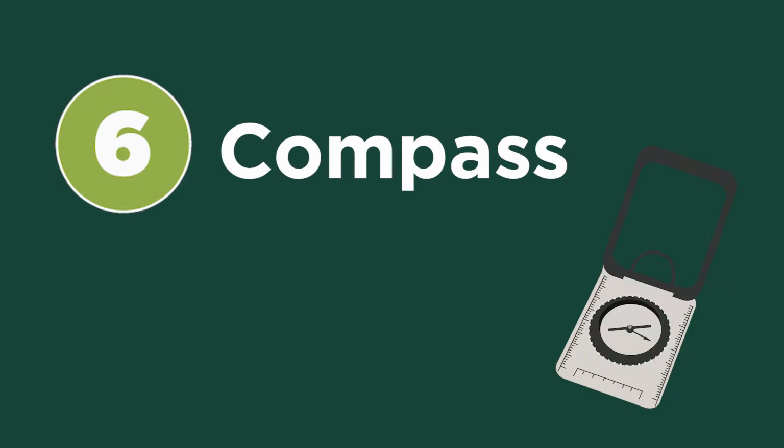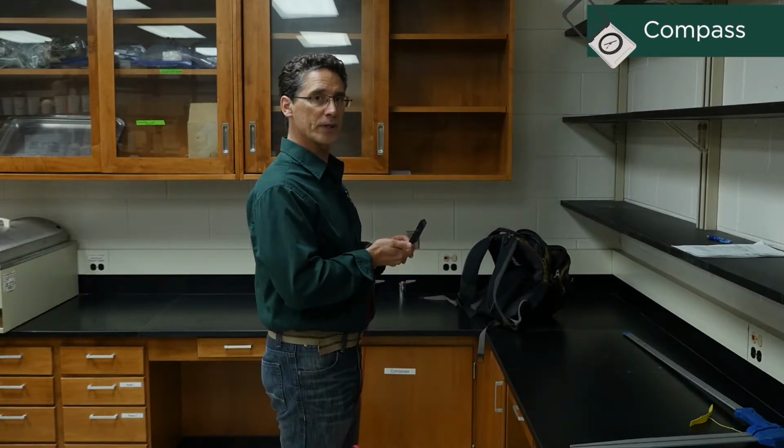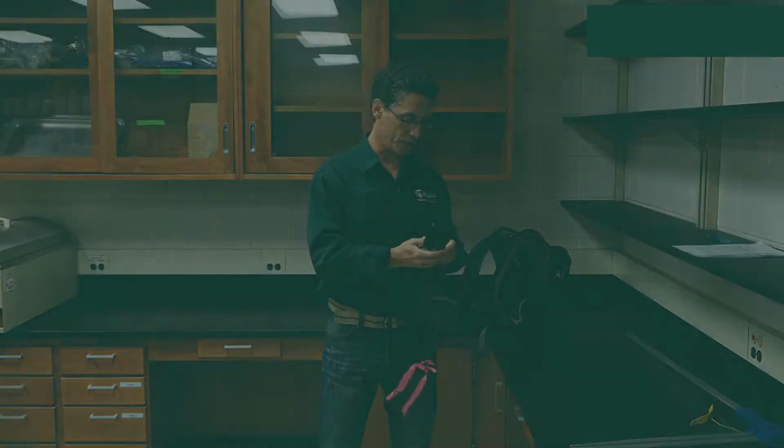Another important tool is the compass. Many of you know that compasses have a magnetic needle, which points towards the magnetic north pole of the Earth. As I turn around, the needle is always pointing to the north, and I can use the dial on the compass to determine what direction I'm facing or determine what direction I want to go in. In forestry, we basically use the compass to navigate around the forest and also to mark the angle as well as the distance with the measuring tape between objects in the forest.